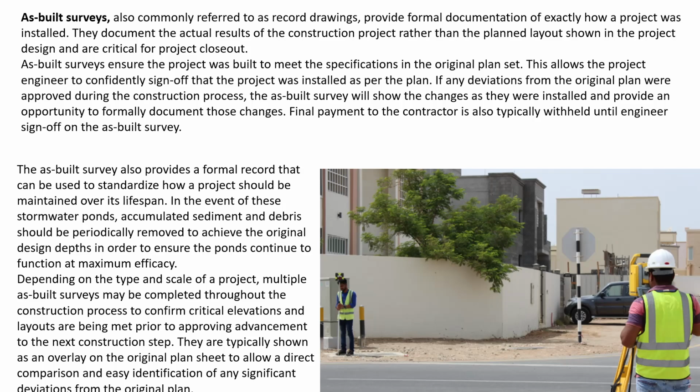Depending on the type and scale of project, multiple as-built surveys may be completed throughout the construction process to confirm critical elevations and layouts are being met prior to approving advancement to the next construction step. They are typically shown as an overlay on the original plan sheet to allow a direct comparison and easy identification of any significant deviations from the original plan.